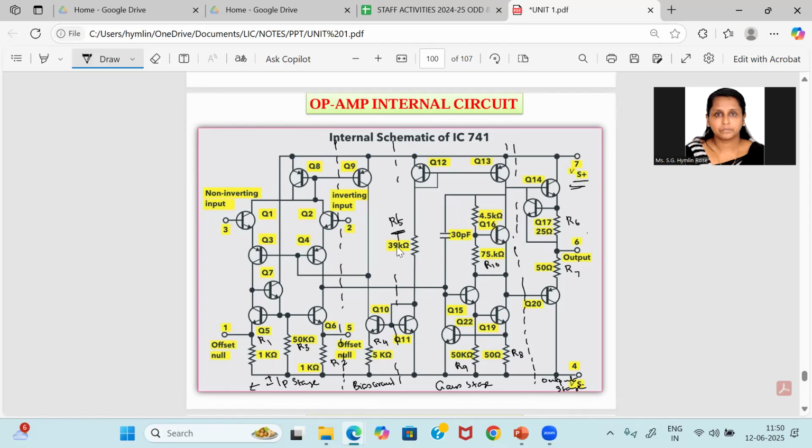The transistors Q1 and Q2 form emitter followers, contributing to high differential input resistance, and whose output currents are inputs to the common base amplifier using transistors Q3 and Q4. Q3 and Q4 offer large voltage gain.